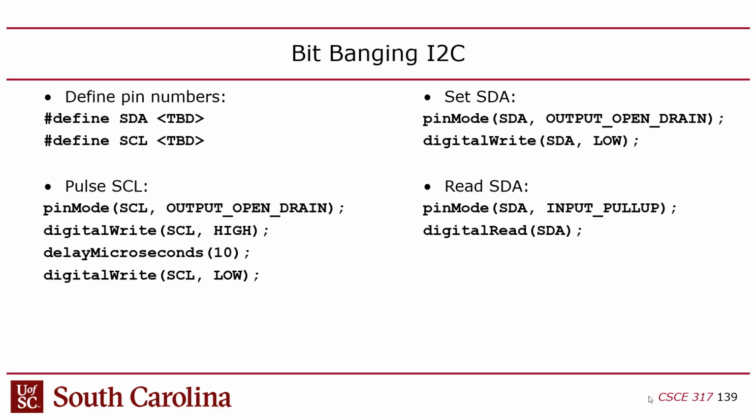Why pull up? That enables the internal pull-up resistor inside the chip. It's not really necessary, because we have an external pull-up as well. I think that was from an older version of the board where we weren't using it. We shouldn't have to since we have external pull-ups. What would you set it to if you don't use input pull up? Just regular input. Okay, there's no reason not to do it.